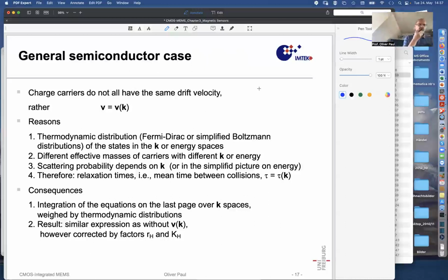now this is more fundamental semiconductor theory. Some of you have heard my semiconductor lecture, actually 2 of you know, the others haven't had that lecture, but you may have seen elsewhere that, for instance, in silicon, if we draw the reciprocal space, the K space that is used to designate the wave functions, Kx, Ky, Kz, then in an area called the first Brillouin zone, we can define some points, and the electrons are actually sitting in K space near those points, in pockets that have this ellipsoidal shape, the symmetry of those points, so different in the longitudinal direction from the transverse direction and two identical transverse directions. And so there are these 6 electron pockets,